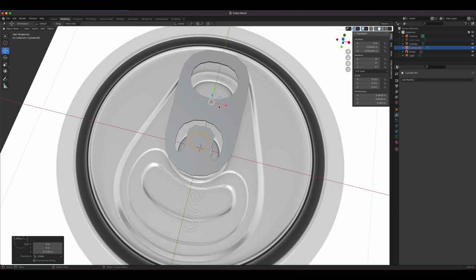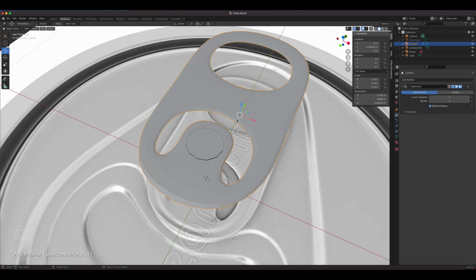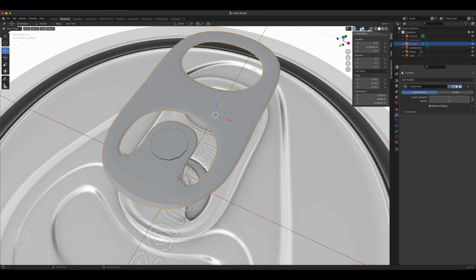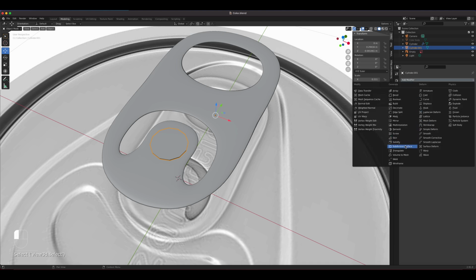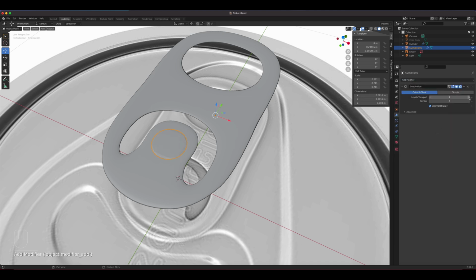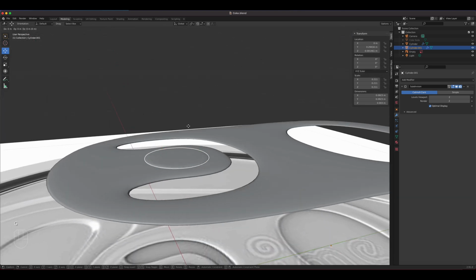If you're not happy with the look, that it looks very faceted, you can apply a subdivision surface to this, which will smooth it out very nicely like so. And you can right click and shade smooth. You can do the same thing with that, or that's just fancy, you could have done just a cylinder on this one. All right, but there you have it.